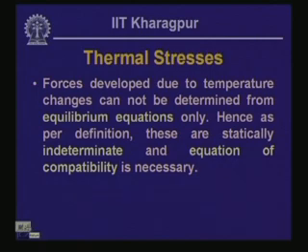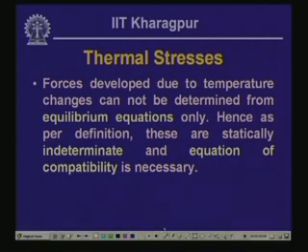Well, the change in temperature causes forces if they are restricted, and these forces cannot be determined from equilibrium equations, as we have seen earlier. Since we cannot determine the internal forces which are getting developed due to change in the temperature, we call these kinds of systems indeterminate systems, according to the definition we have seen earlier.